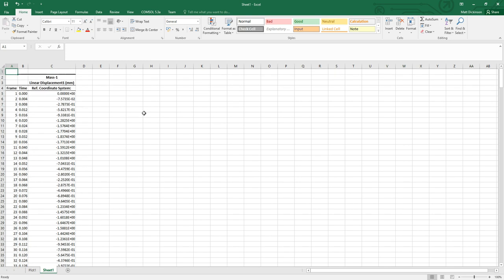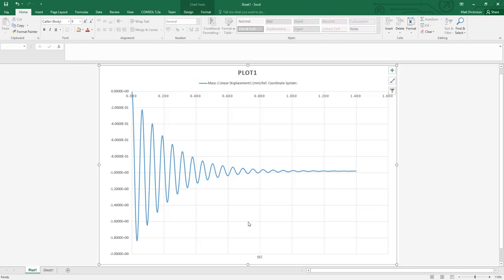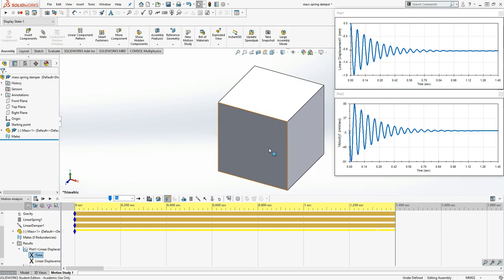One thing to always keep in mind if you are going to do verification is make sure you look at the time step, make sure your time step will match against it, or make sure these things are considered, or else you'll end up plotting something and it will be a factor of 100, 1,000 or whatever out of what you want to do. It is a very useful tool, really useful tool.